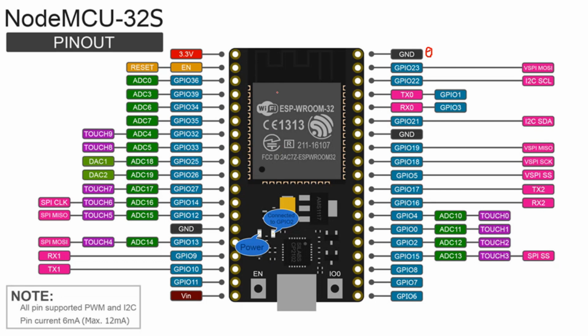GPIO is nothing but general purpose input output. Through that only we can enable everything. You have to connect with the device, so there it can act as an output pin, and an input pin also. There are some sensors, like ultrasonic, where we have the input as well as output. It will send the signal and then it will receive the signal.